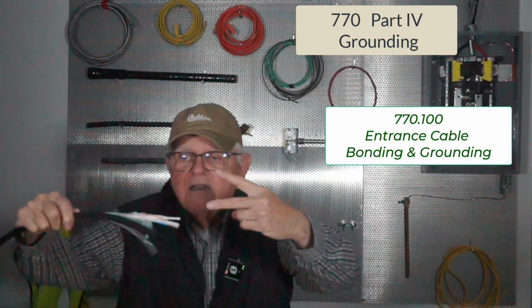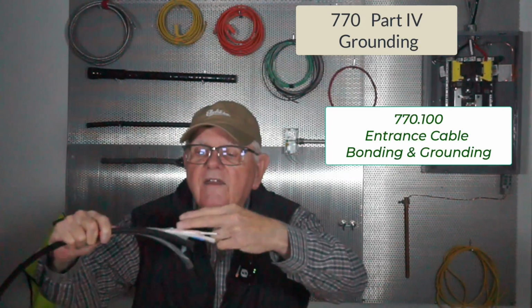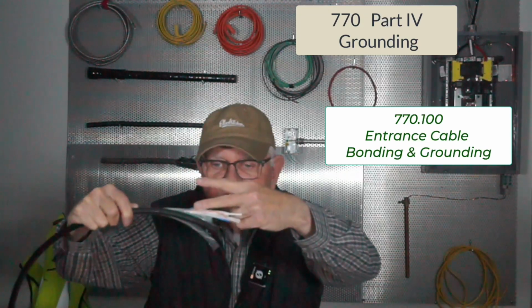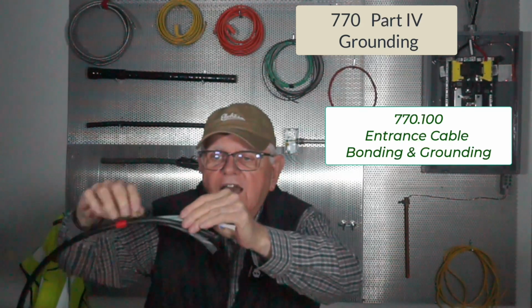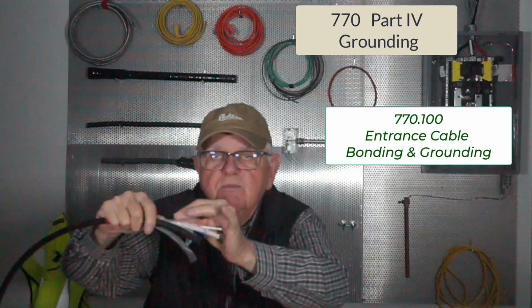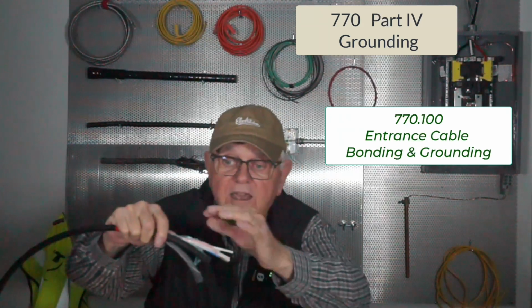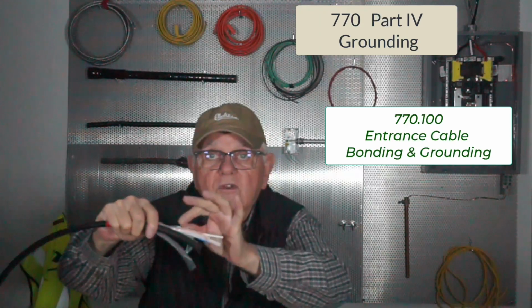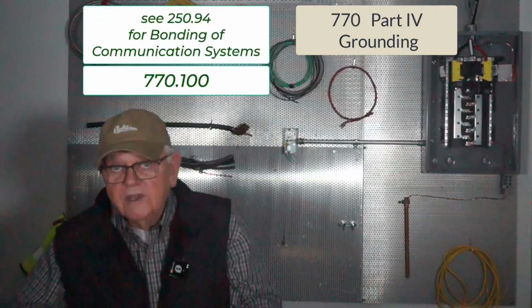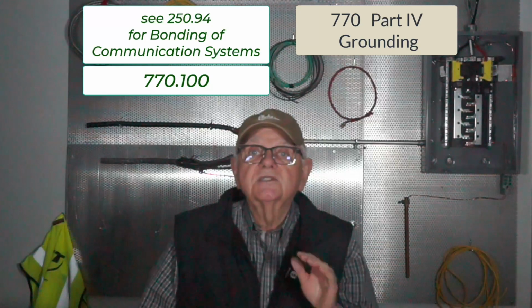wedge, and I'm going to take and slip that wedge between the filler and that metallic sheath. And it's going to clamp down on that metallic sheath then. And when it clamps down on that metallic sheath, I tighten the bolt down, sticking up on the stud. I can attach my equipment grounding conductor, a bonding jumper really is what it is, right? And I attach my bonding jumper, and from there we have to get back to 250.94, and we have to take that bonding jumper from where we enter the building, and we have to take it to our intersystem bonding